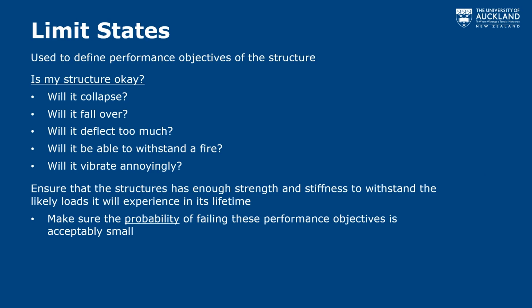And so if we go back to thinking about these limit states, what are the performance objectives? And it really comes down to this question, is my structure okay? Will it collapse? Will it bend too much? Will it be able to withstand fire? If someone's sitting at a desk on the floor, if someone runs by, will the floor vibrate? Will it move a lot in the wind?